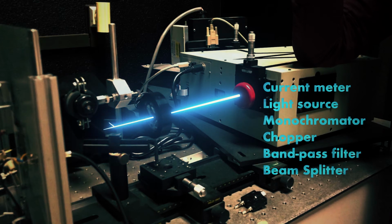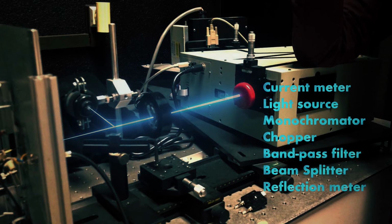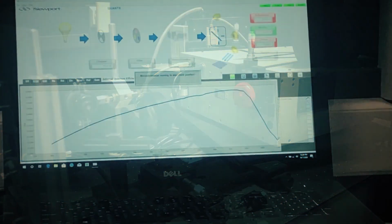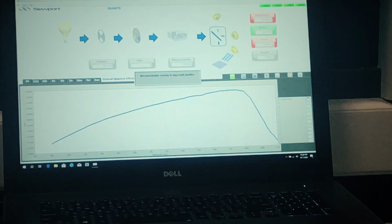The beam splitter can divide the radiation in different fractions, and it is suitable for this type of systems as long as we know how it divides the proportions of light, allowing us to determine the relation between the optical power that arrives in the reference and sample photodetector. A reflection meter to monitor the amount of light that is lost by reflection, either on the encapsulation or on the photodetector itself.